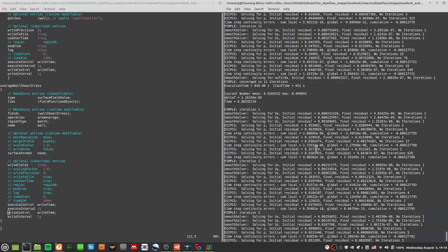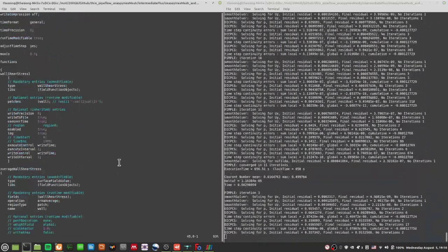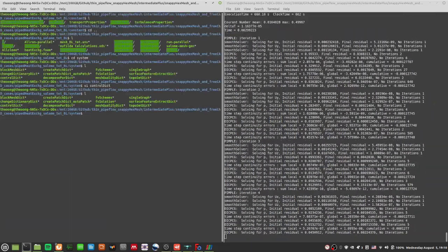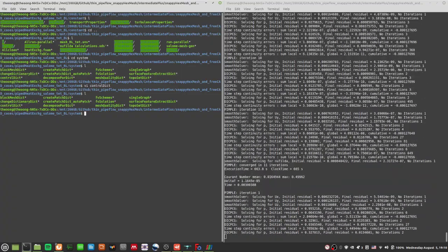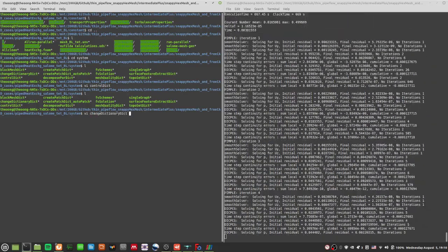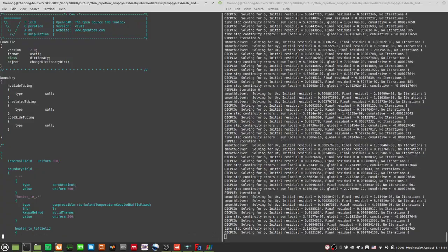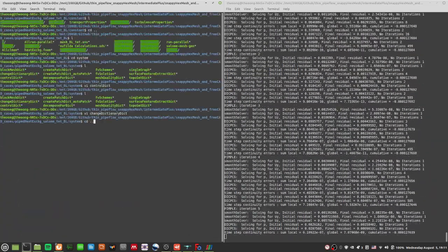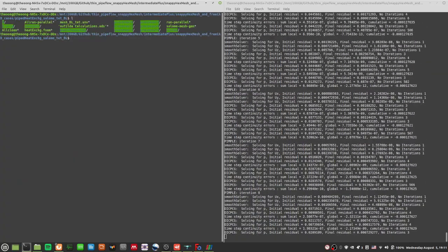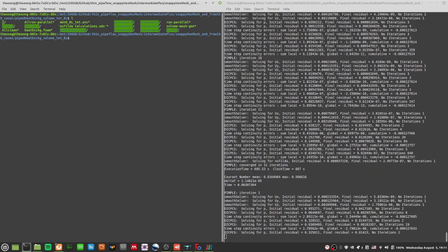Okay, so this thing looks pretty stable. The mesh looks good. Okay, it's stable, so it doesn't really need too much attention in that sense. The next thing is of course changeDictionary, so that changes all the patch types here to wall. Nothing too much there. Everything else is more or less the same. I didn't change anything else. It's just the geometry and boundary conditions. All the rest of the things are the same.